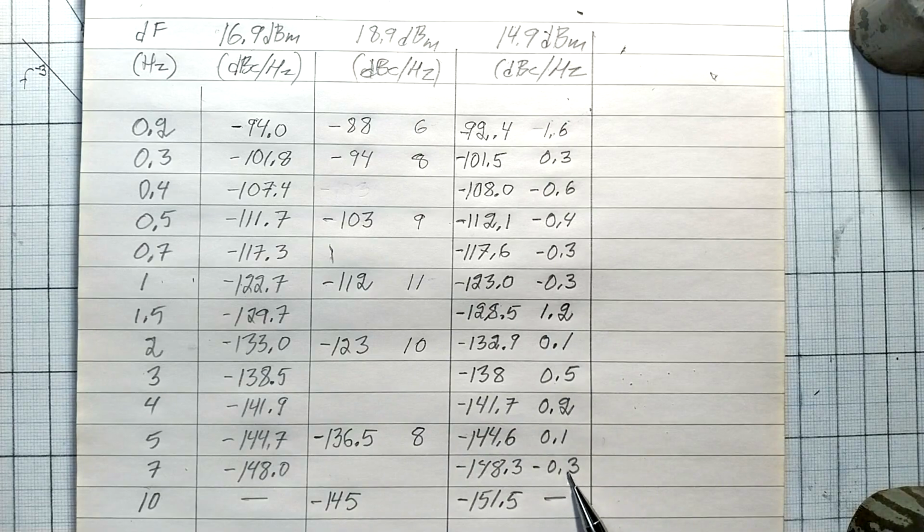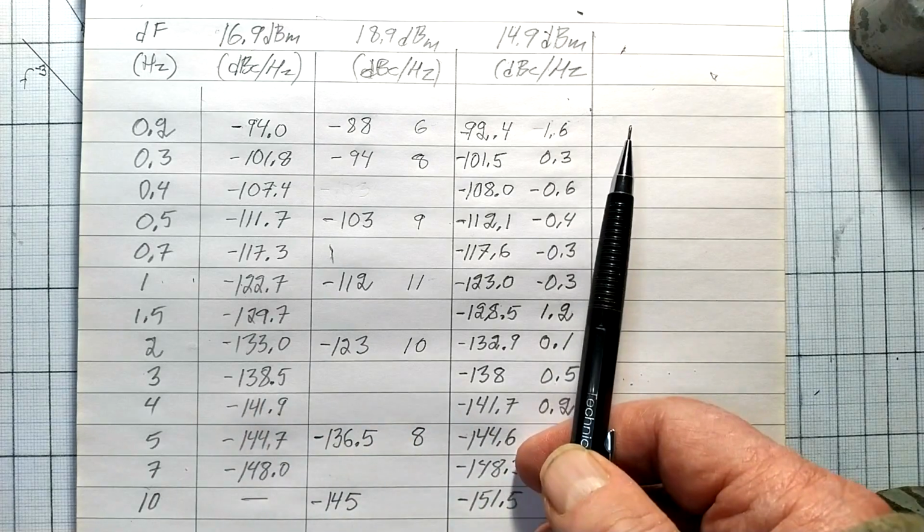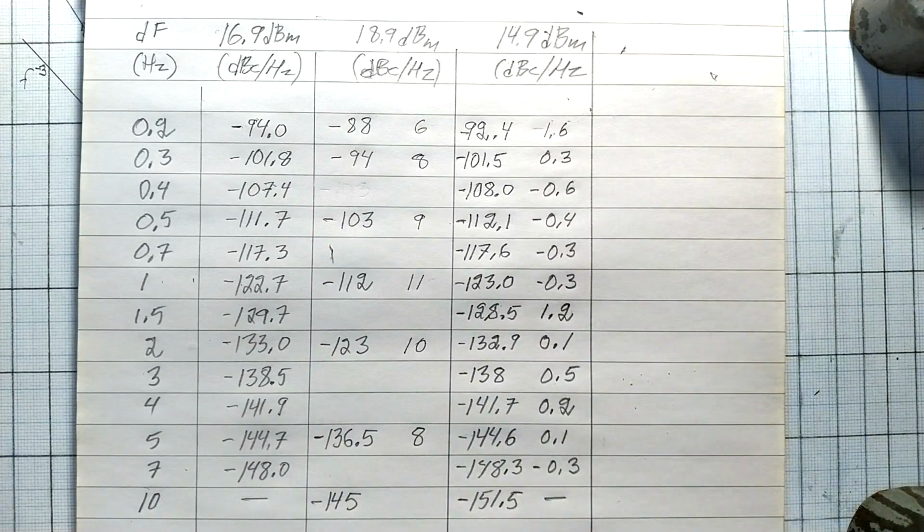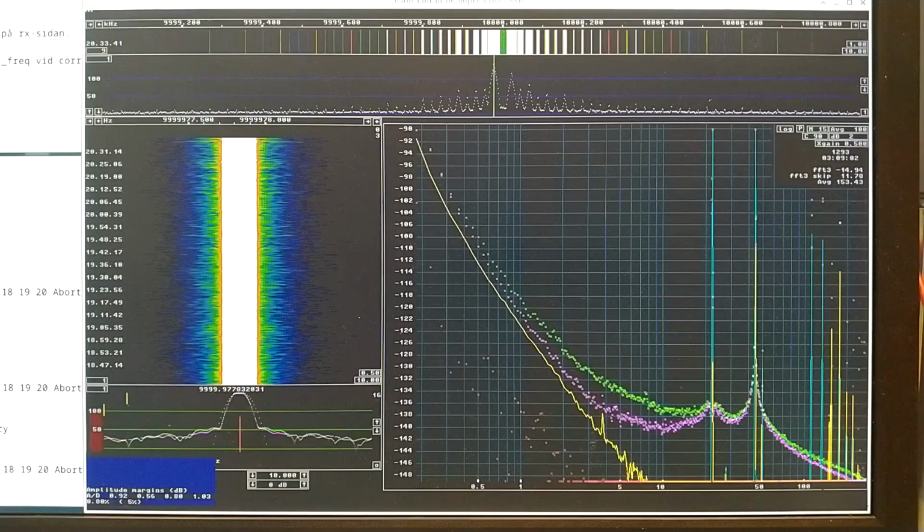And then the values are small, probably not significant here, because statistics is not so good down here. Anyway, this looks like a hockey stick, famous from the climate debate. Very flat and then suddenly up with increasing power. I have run the calibration procedures for Linrad to flatten the frequency response when I go up to 10 kilohertz or above. Now, that didn't work well because the calibration algorithm introduces some spurs.